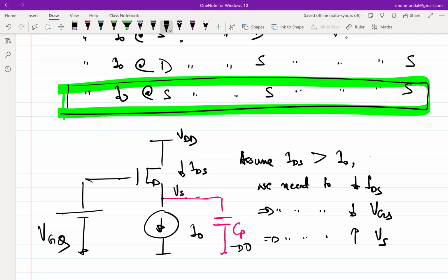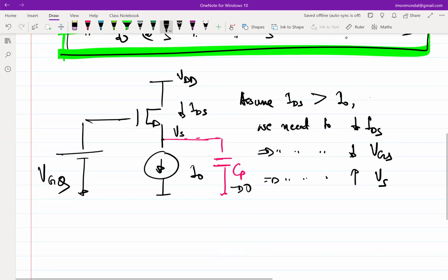Her point was, it seems like the sense of the direction of the correction is fine, but how do we know that it is enough or not? How do we know the transistor is in saturation or not? Right? So firstly, what will ensure that the transistor is in saturation? Which condition will ensure that? Yeah, only the difference between these two voltages, the drain and the gate. Both the drain and the gate voltages are in our control, so we can set them as we please. So that ensures the transistor is in saturation.